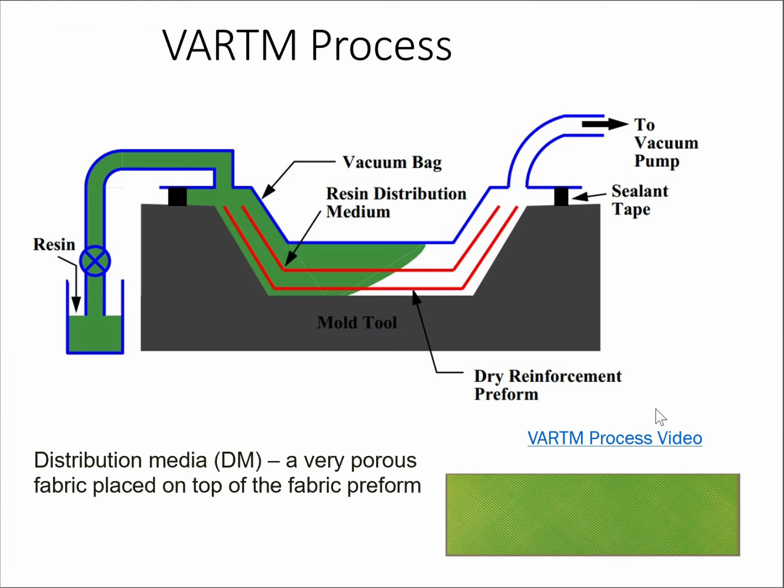VARTM takes it a bit further as well. So this whole process is going to be guided by creating a vacuum. You have your mold. For us, the mold is just a flat table because we are just going to create composite plates. You seal your preform, just essentially put a sealing plastic on top of it. You have an inlet for the resin.